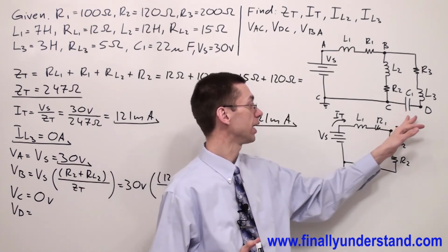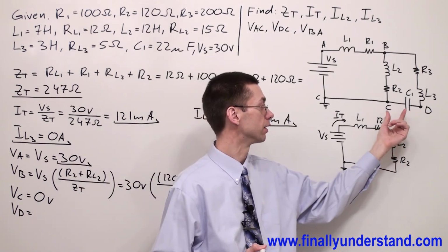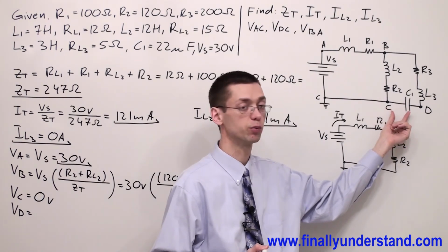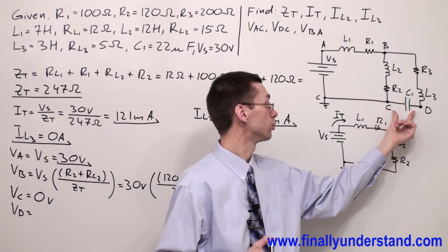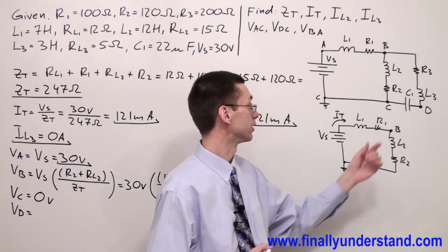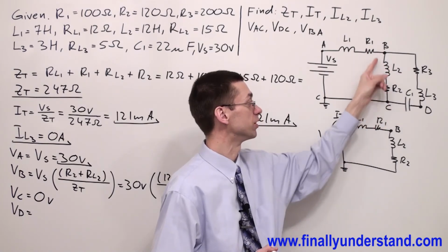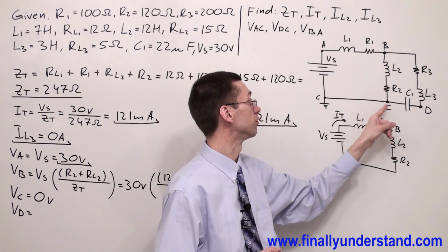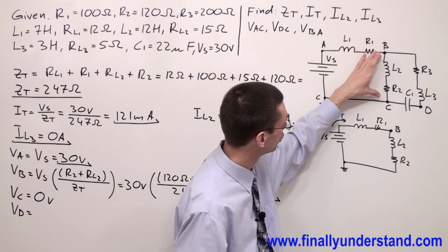So the capacitor, having the largest impedance, because it behaves like an open circuit, meaning it has extremely high impedance, is going to concentrate across itself the maximum voltage, and the maximum voltage in this branch is simply voltage VB, because the sum of these voltages is supposed to give me voltage VB, the voltage which appears across these two components.